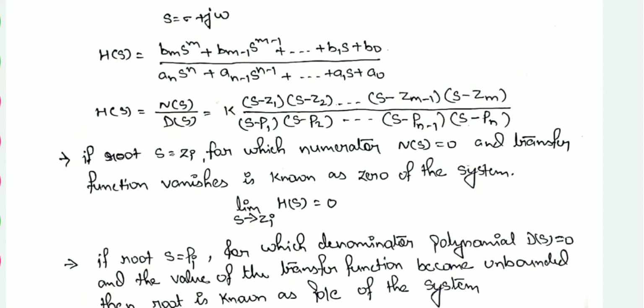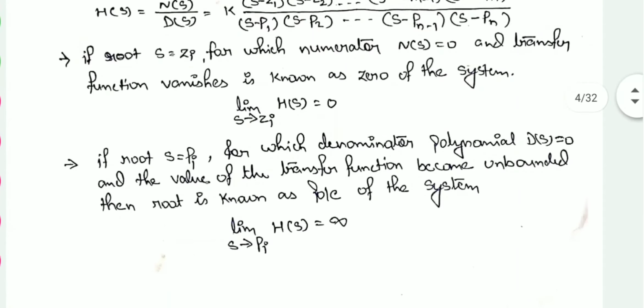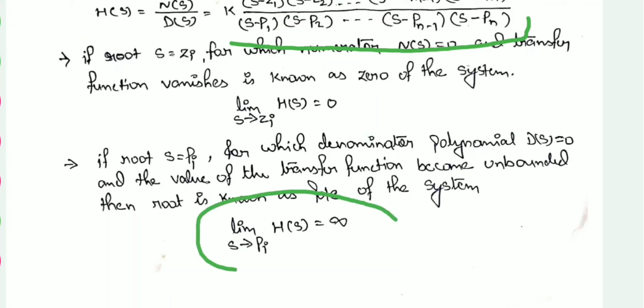Similarly, from the denominator side, when we put the roots, which are p1, p2, up to pn, into the transfer function, the transfer function becomes infinite.